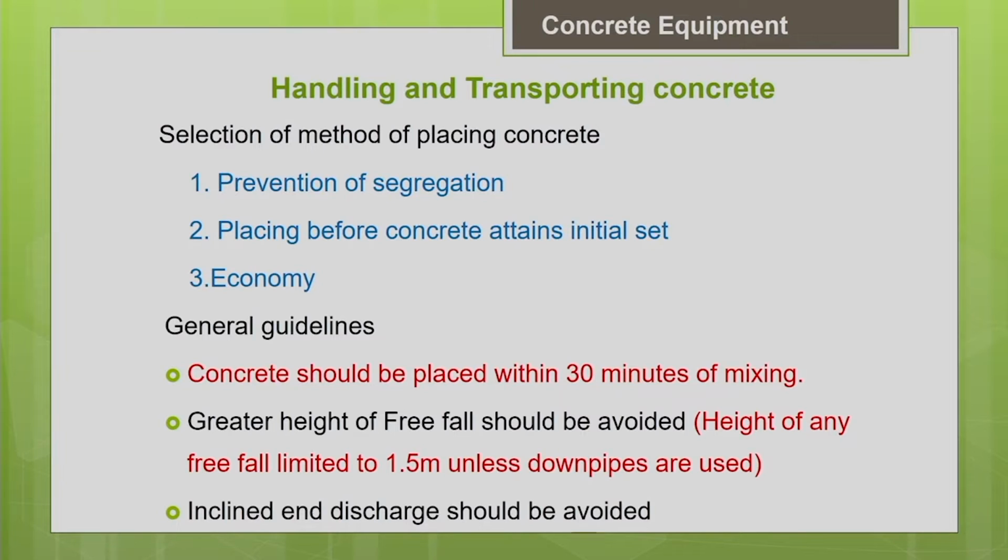So, very commonly you can see that people put a lot of effort into the mix design of concrete and in the preparation of concrete, but very often they do not care much about the method of transporting the concrete. If you do not carefully transport the concrete to the desired place, during transit the concrete may get segregated. If segregation occurs, you will not get a homogeneous microstructure in the concrete, and that is going to affect the strength and durability of your concrete. That is why we need to put proper effort even into selecting an appropriate method for transporting the concrete.